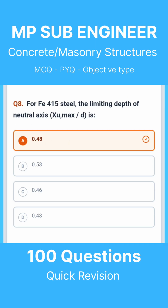Question 8. For Fe 415 steel, the limiting depth of neutral axis, xu,max divided by d, is. The correct answer is 0.48. Question 9. For Fe 250 mild steel, the limiting depth of neutral axis, xu,max divided by d, is. The correct answer is 0.53. Question 10. For Fe 500 steel, xu,max divided by d is. The correct answer is 0.46.